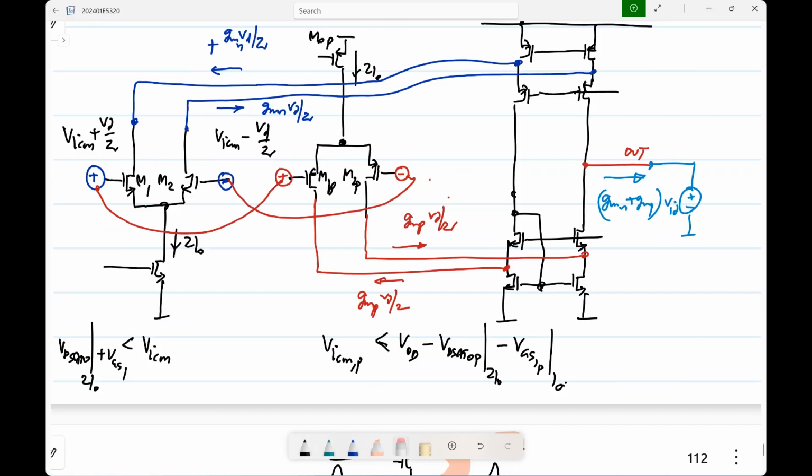Okay. Now the other type of op amps that we saw were these multi-stage op amps. Okay. So where essentially we tried to improve the integrator. This gave us 2 and 3 stage Miller compensated op amps. There were also feed forward op amps. I will discuss them only after we come to fully differential op amps, because typically, after the 2-stage op amp, we'll move to the fully differential op amps.